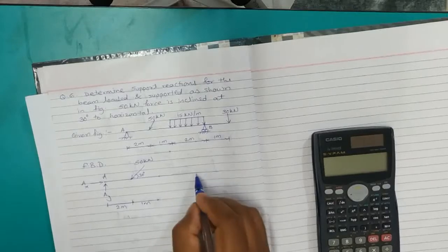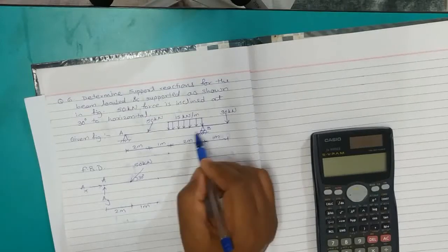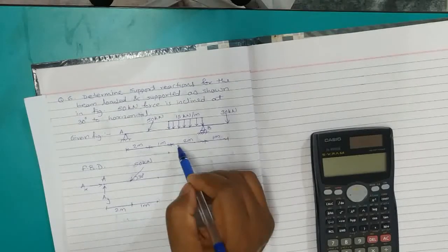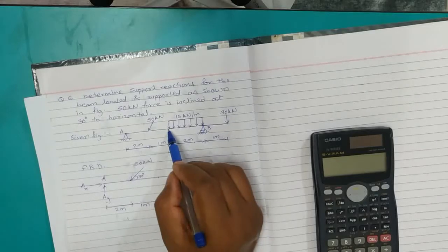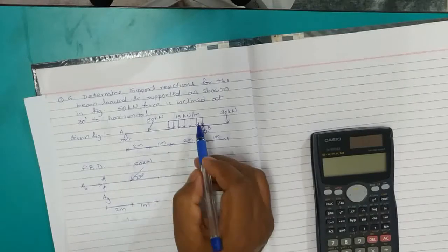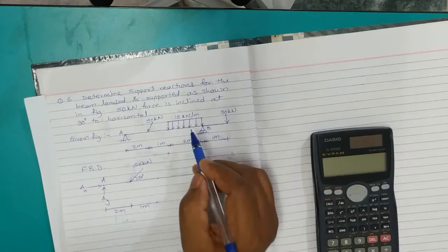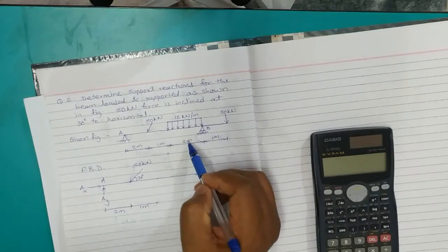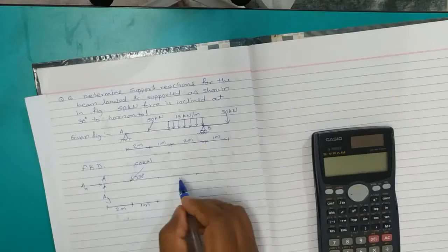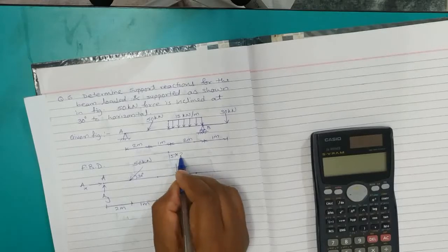We know that for a rectangular load, if we want to find out the equivalent point load of this, we'll have to calculate the area of the rectangle. The intensity itself represents the breadth and the span, the 2 meter span on which the uniformly distributed load is present, that is 2 meter. So length into breadth, that is the area of the rectangle, and that will be the magnitude of the point load. So 15 into 2, 30 will be the magnitude of the point load, and it should be located exactly on the midpoint of this 2 meter span.